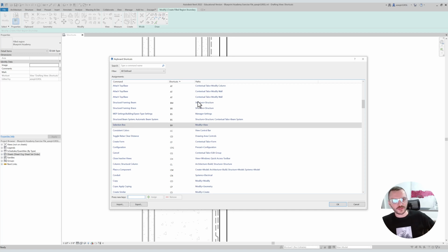You should never look at stair drawings just in plan. You should have side-by-side windows of a 3D view with the cut maybe in section. You can see all the landings are exactly where they need to be. You can see visual cues. You should have an actual section drawing posted up as well. Again, just hit WT for window tile.